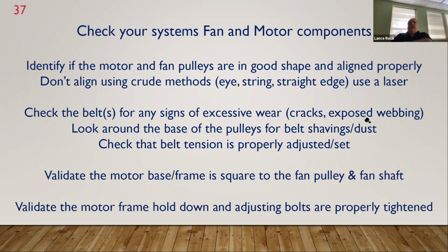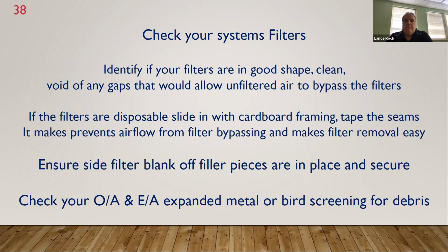Check your system's fan and motor components. Identify if the motor and fan pulleys are in good shape. Don't align with anything other than a laser. Check that the belts are not excessively worn or cracked. When you have adjustable pulleys, they're only for balancing at startup. Replace them with fixed pulleys, and you will have belts that can last 10 years. Absolutely last 10 years. Next, please.